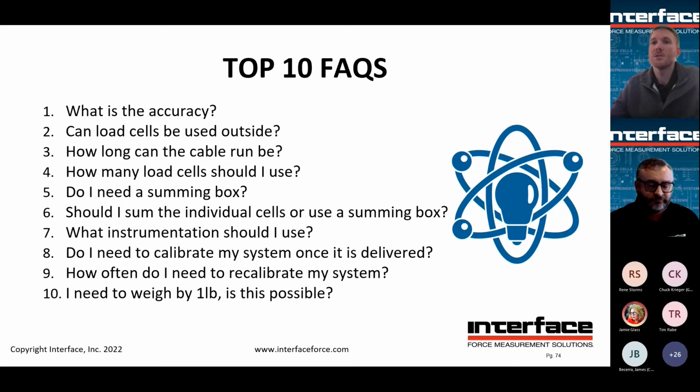How many load cells should I use? Well, it depends on how many legs you should use. If you're at the beginning stages, one thought is always that 3-legged stable milk stool compared to the wobbly 4-legged structure. Sometimes you're going to do 8 or more, but just consider that all of those need to be on the same plane, and getting 8 weigh modules and load cells on the same plane can be difficult.